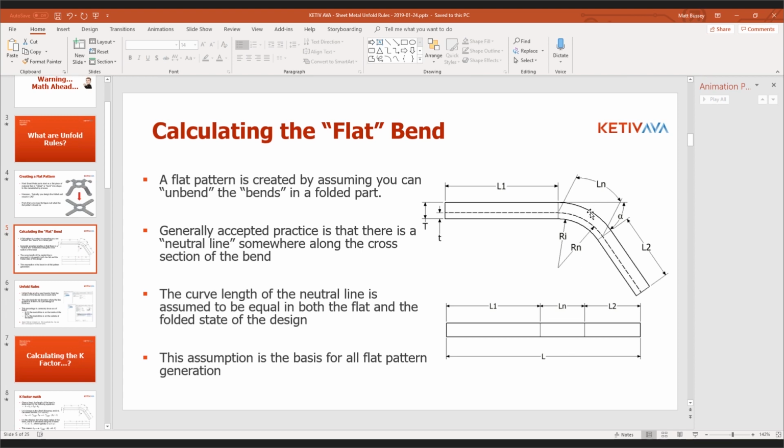When you bend metal, this thickness right here thins. Part of the reason this works really well for metal is that the amount of thinning is so small that the error in making this assumption is, in most cases, negligible. It's tens of thousandths of an inch or less.